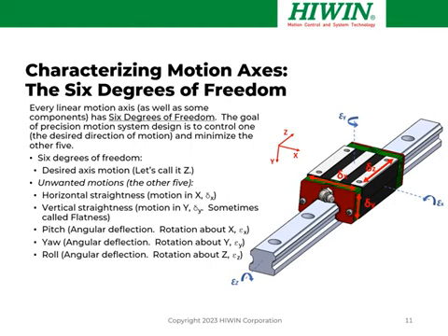And those are the ones that really add up, and they're the ones we really want to try and minimize, because those are especially what contribute the most to AB errors, because they are positioning errors caused by deflections, angular deflections in the motion system. And experienced motion engineers, we know how to design motion systems to minimize those errors. And when you analyze all the errors in a multi-axis system, it starts to get really complicated, and we'll talk more about that in a few moments. But all of those components are used to form the error budget.